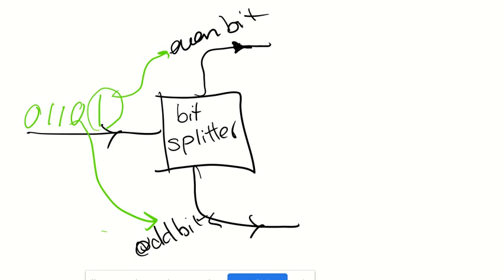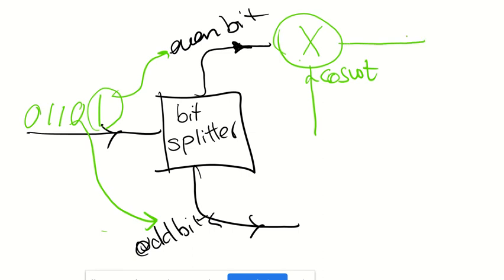That's the idea. One by one, they go and sit on different signals to be transmitted. And then here you have a mixer, by which I mean that you have your cosine signal. So you have your analog signal that will be mixed with your bit information, in this case 1 bit, and it will go here. Okay, so what's happening here? Remember I talked about BPSK. I said 1 bit of information if there is one phase.